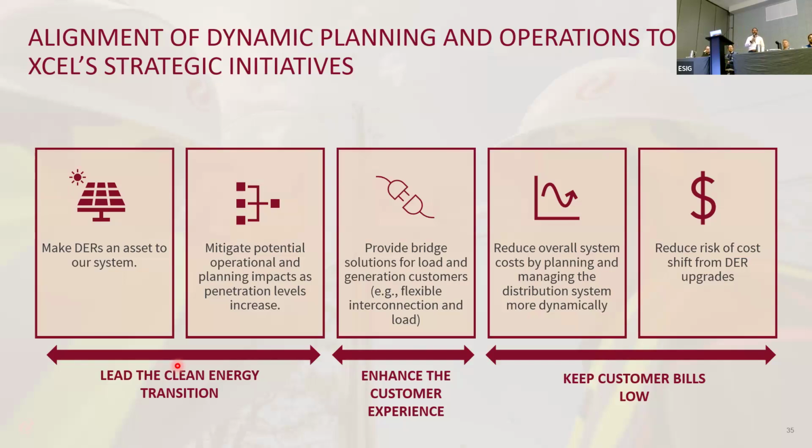So we're starting to see clustering of massive amounts of load growth from a residential perspective. Think about examples we've seen where a customer may put in some rooftop solar, and then they go get an EV, and then they go get a heat pump, and it's got electric resistance backup heating. So you're talking about going from what may be 6 or 7 kW of demand on a residential household to tripling in the span of a couple of months.